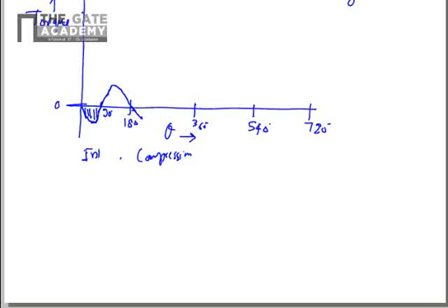0 to 180 degree is intake. So during the compression, entire energy is taken from the crankshaft to compress the gases. So here the torque on the crankshaft will be negative. Energy will be taken from the crankshaft. Crankshaft will be decelerated. So 180 degree to 360 degree is complete negative energy, negative torque.